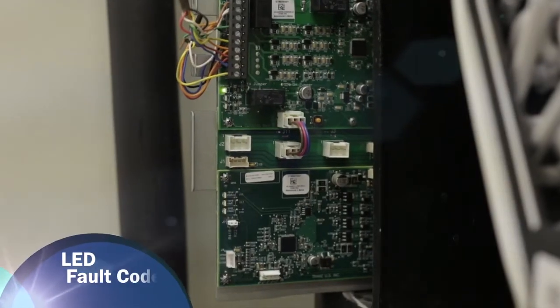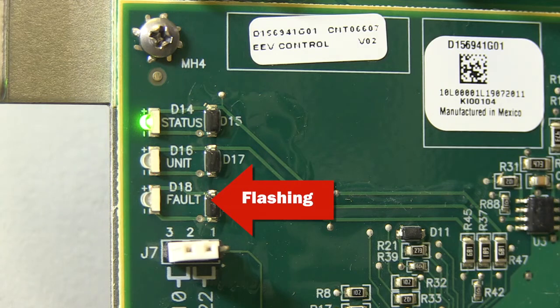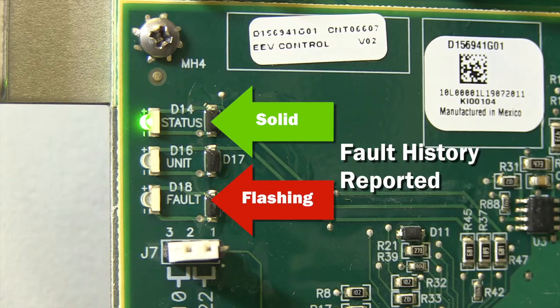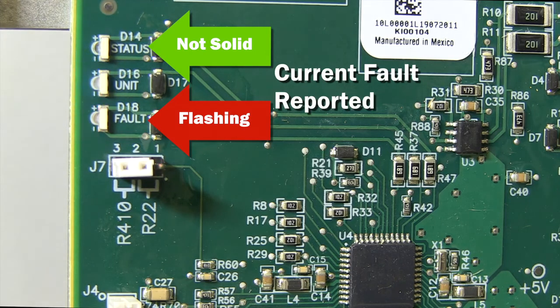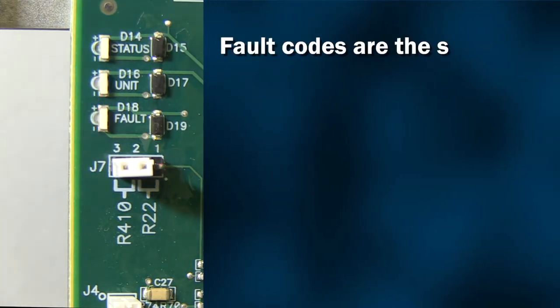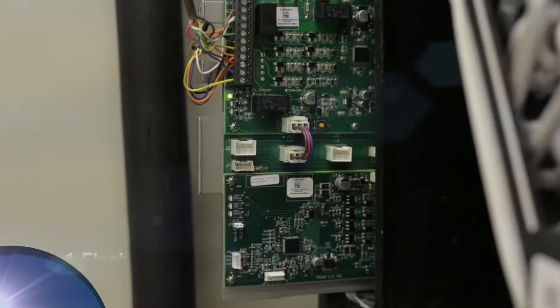LED fault codes. Following the power-up sequence, the red fault LED reports EVC faults. If the fault LED is flashing and the green status LED is solid, the system is reporting fault history. But if the green status LED is not solid and the red LED is flashing, the fault codes being reported indicate a current fault condition. Fault codes are the same for fault history and current faults, and we are going to cover them one by one next.